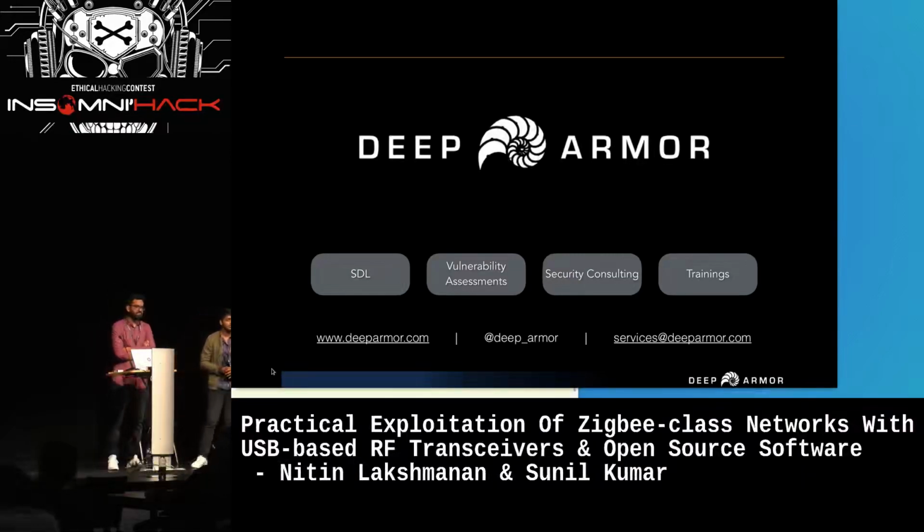Thank you for your presentation. How are you able to capture packets if you don't have the network key of the Zigbee, or did I miss something? So 802.15.4 just publishes the packets in the particular channel. So anyone who is sniffing in the same channel will be able to capture the packets. Okay, so the payload isn't encrypted by the network key. Yeah, for this custom packet, it's not encrypted. Only integrity is maintained.